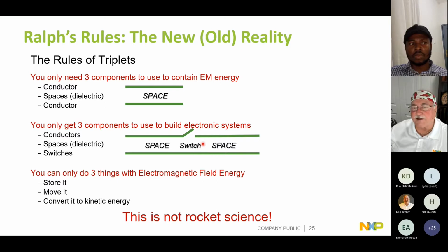That is how it sees that it needs to move to this new space: it sees spaces where the charge has not been displaced. And so that displacement current occurs at the wavefront as this energy starts to move into here. The faster the switch turns on, the faster the energy displacement has to occur.